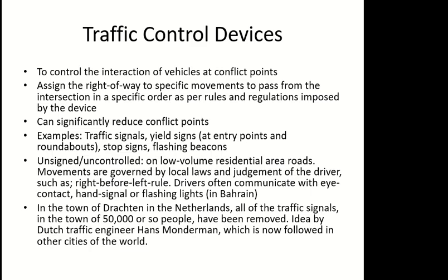That's why we go for the signal as the last resort, as the last option. So we try to use the other types of traffic control devices, stop sign, yield sign, uncontrolled, before we go on to the signal. And we will later discuss why in some cases signals become necessary.